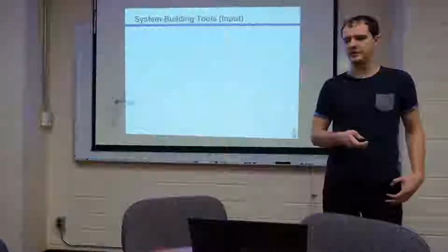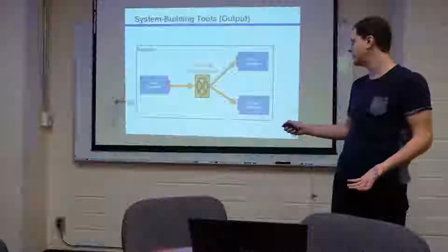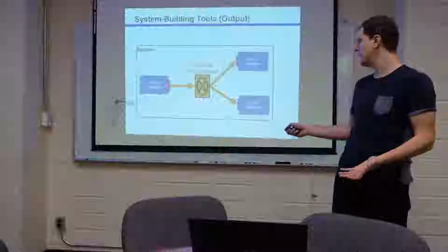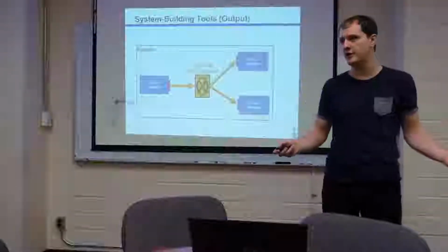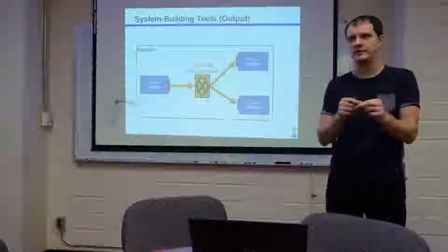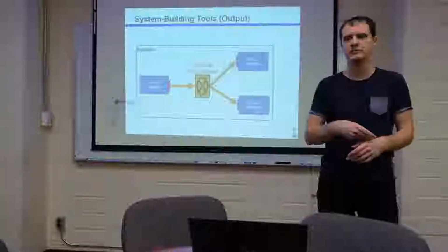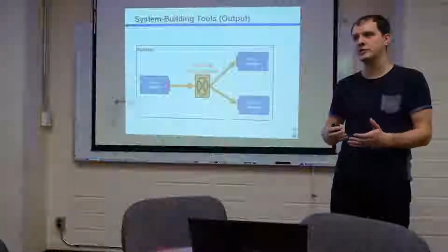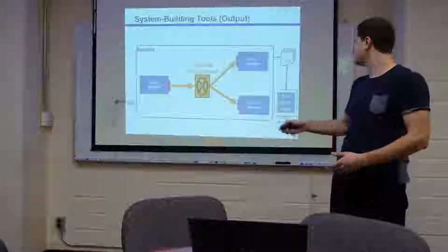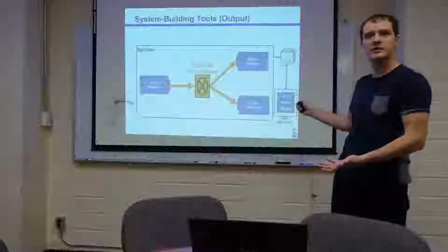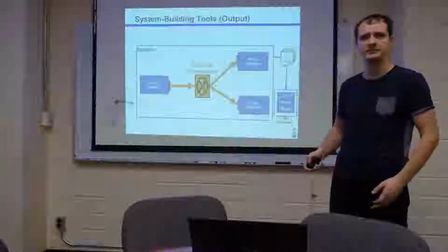So what the tool does, after you give all these inputs, is it creates a system that instantiates the modules that already existed, and it turns those logical links into physical interconnects. I'm using the word interconnect in this talk. I don't mean the wires inside the FPGA that an architect would care about, the low-level wiring and the switch blocks and all that stuff. No, this is soft interconnect that's made using logic, and essentially this tool relays this as Verilog, which then goes to a proper CAD flow. So that's the final output of these tools.